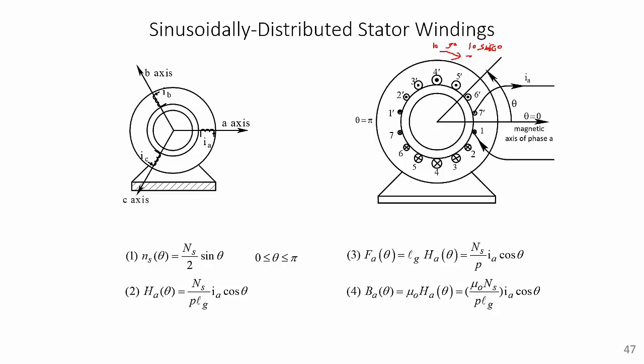That comes out to approximately 9 turns in the slot that is 30 degrees away. Another 30 degrees away, the number of turns at slot 6 would be equal to 10 times sine of 30, which is half the number of turns, so 5 turns in that slot, and so on and so forth, up until we reach 90 degrees from the initial angle, at which point the number of turns in that slot would be equal to 0.